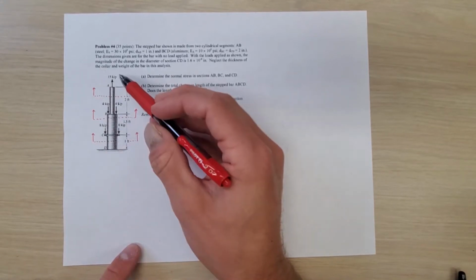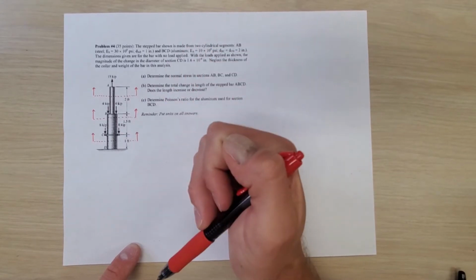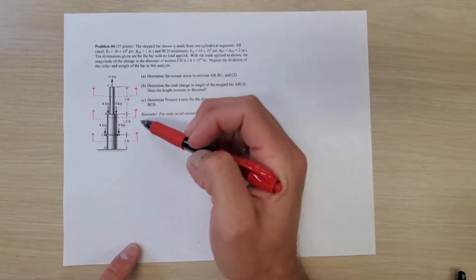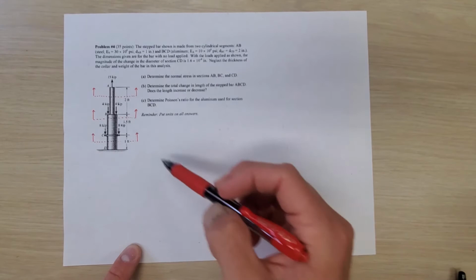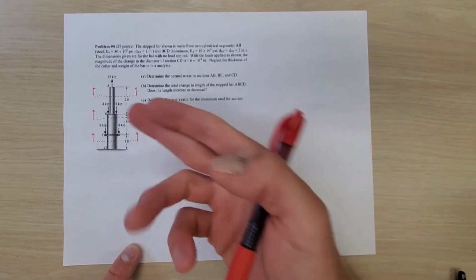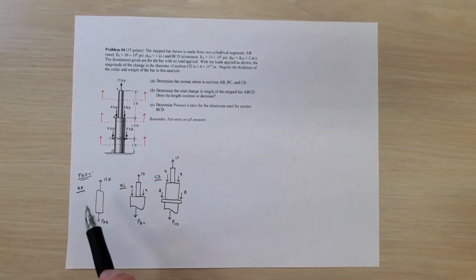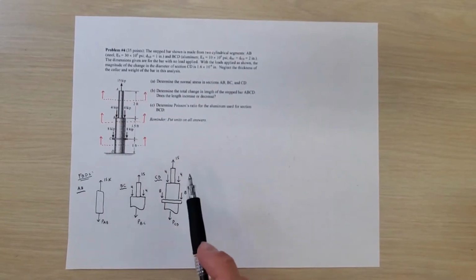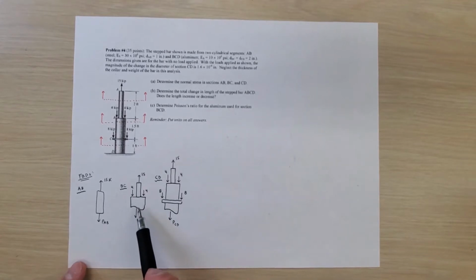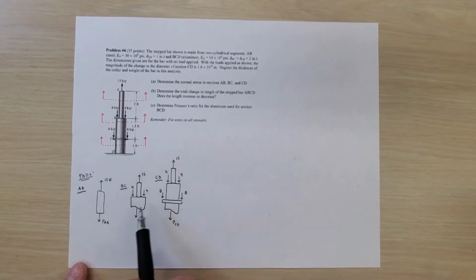I want to just look up and see only the forces that are applied, and that'll make my life a lot easier. So what I'll do now, with these three section cuts, right here in this bottom section of my paper, is draw the free body diagram for each section, and then we'll solve for the force in each part of the rod. So you can now see I've drawn the free body diagram for sections AB, BC, and CD. I've drawn this little wavy line down at the bottom just to show that it's a segment cut, but I forgot to do it down here, but either way, that's what that means.